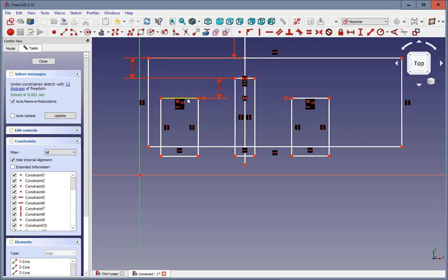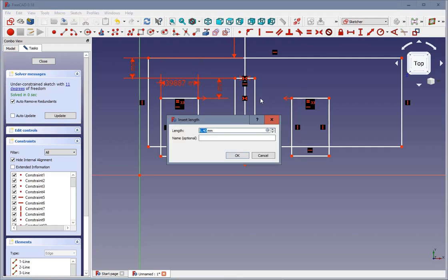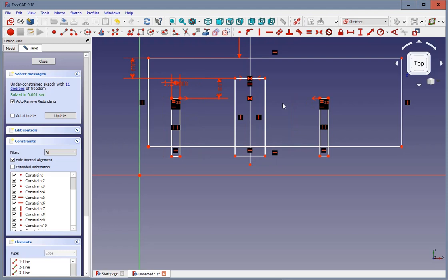So then we need a wall thickness so that the plastic wall goes in here, and the wall is 1 millimeter, but I found out 1 millimeter is not enough because 3D prints always have the tendency to be a little bit tight on insides. So let's give this 1.2 millimeters of distance. That turned out to be the right value.